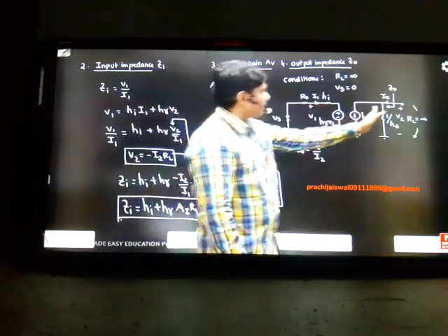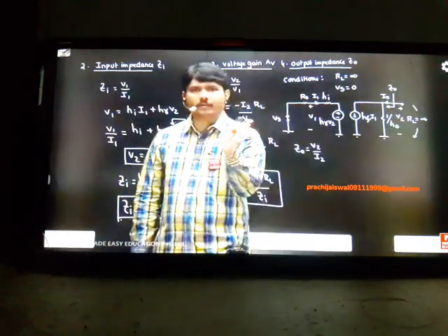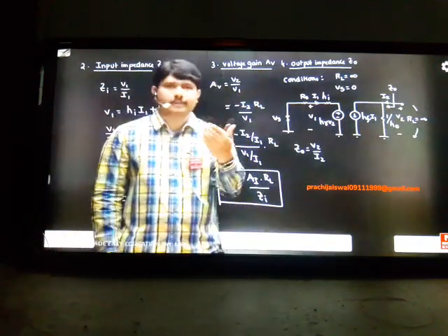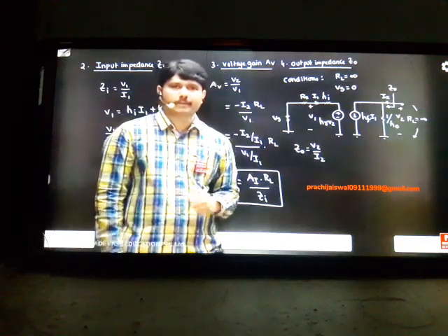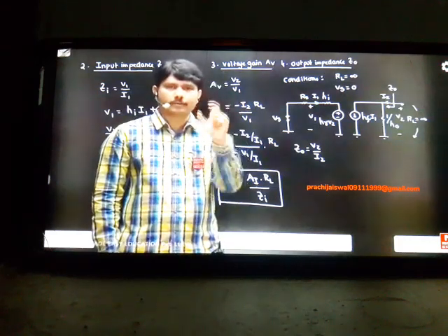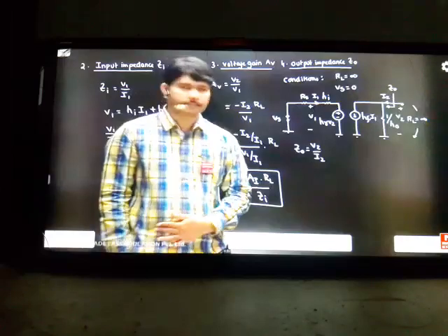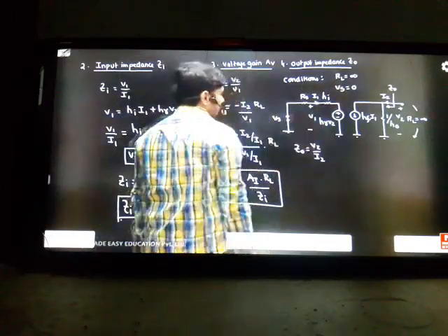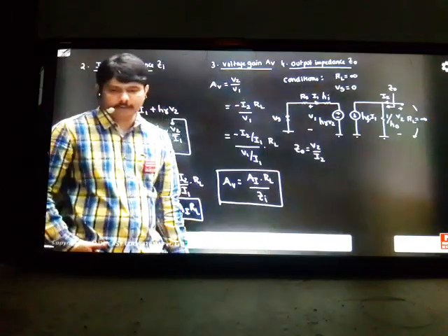So when you're finding from here, load is not interfering with your concept. That's why he said remove the load. First point: remove the load, which is not influencing your problem. And input sources, whenever you cannot find out the impedances correctly, short the voltage source. If there's a current source, suppose, you have to make it open. These are the basic rules he's telling. Simple things. So nicely I have written step by step here, then you should not get this type of confusion. Again you should not ask to repeat.